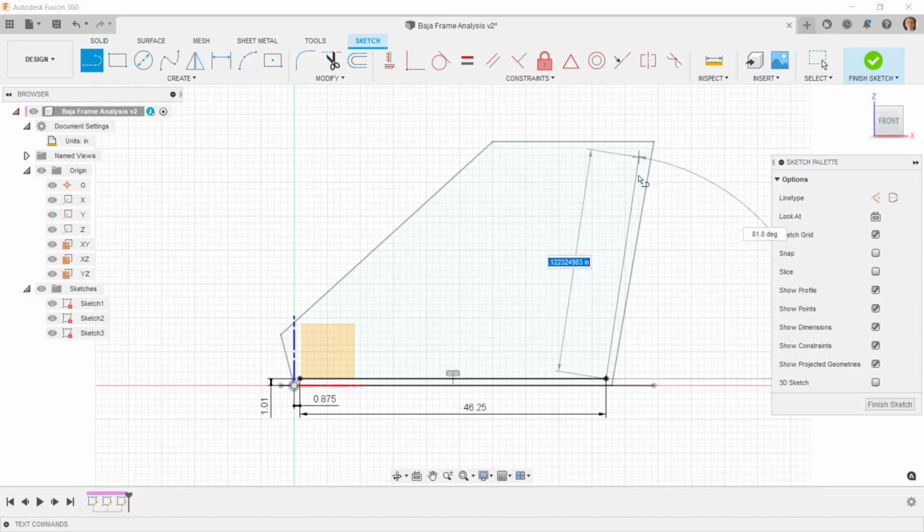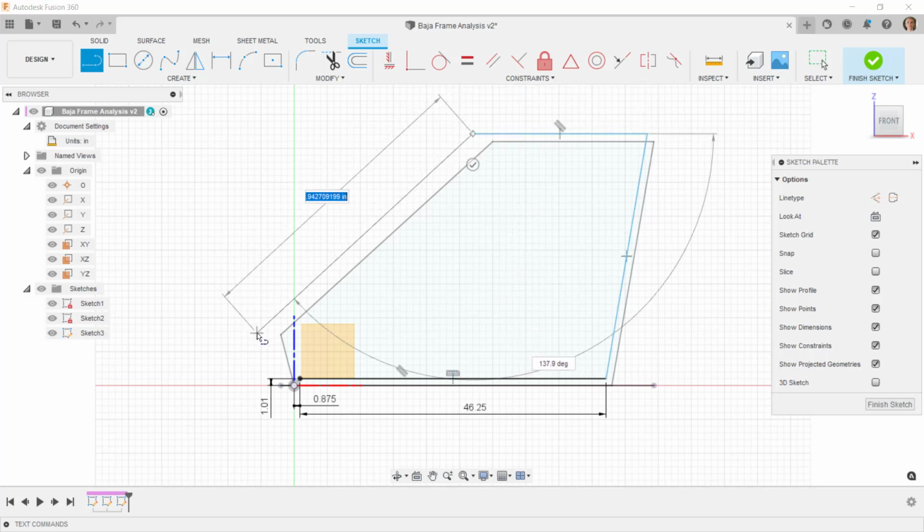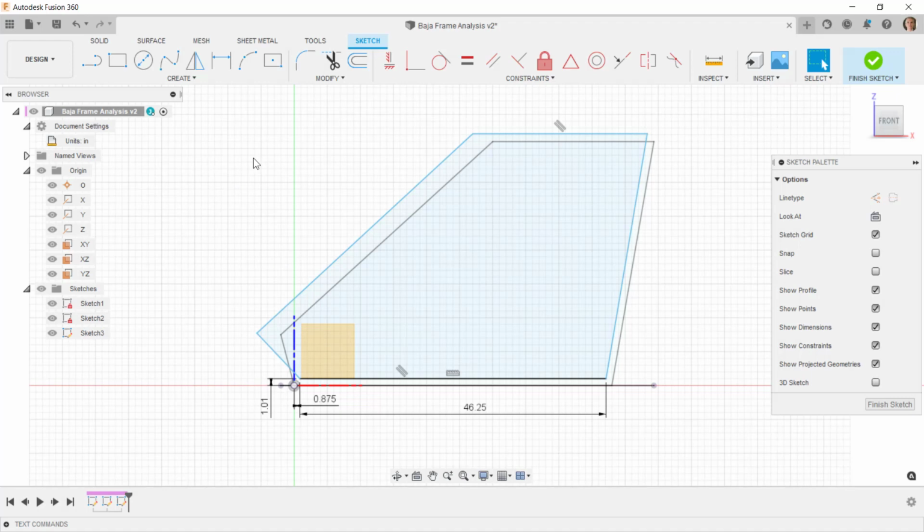I'm going to go a little bit above sketch number 1, and I'll come over horizontally, or either horizontal or parallel to the first line that we did. And I'll come out here and I'll come back to this point, not to the origin. I'll come back to this point. Okay, I'll put some dimensions on here. So I'll dimension the angle from here to here as 80 degrees.